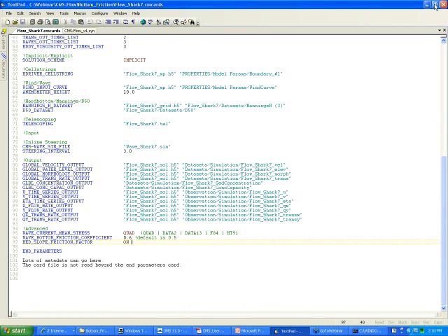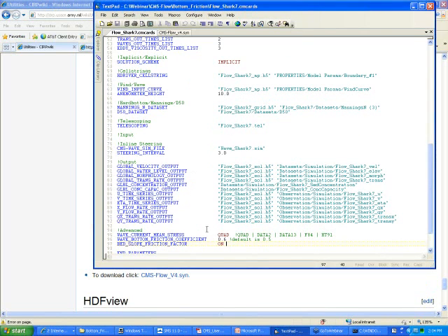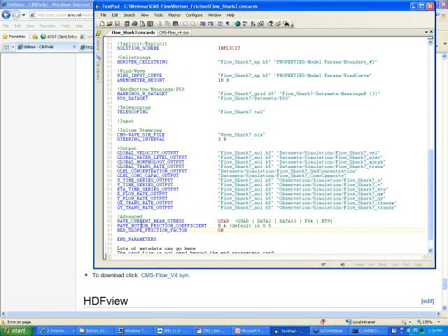So if you want to change something simple like a bottom friction parameter, it's a lot easier to edit the same cards file than to load it in SMS, change it, and save the whole thing again. SMS will save everything, the grid. It's a big grid that you're looking at, over 100,000 cells, and it's going to take a lot of time to load it and save it. A lot faster just to edit the same cards file.